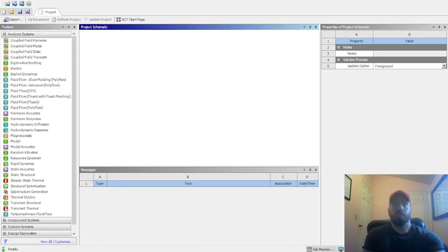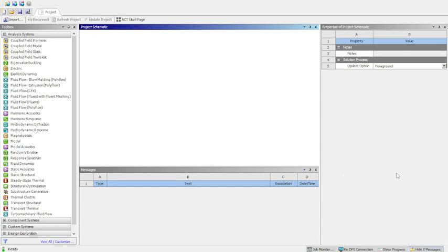Hi, I'm Michael Yosley, and today we're going to be doing a 2D simulation of a CD nozzle in Fluent, and this is for high-speed aerodynamics. Okay, we're going to start by opening the Workbench, and then we're going to drag our Fluid Flow Fluent into the workspace area.